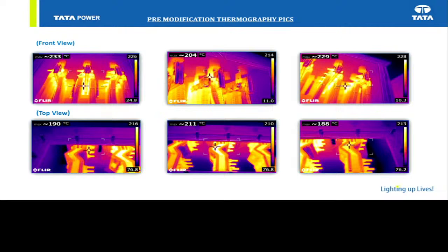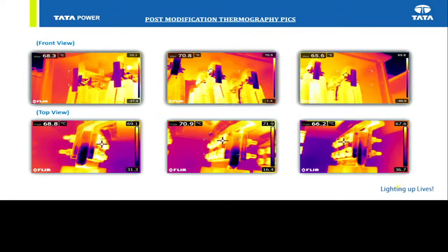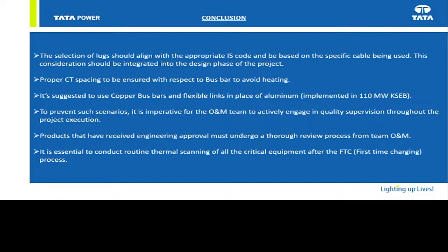For that, we also installed temperature sensors in the LV ducts. But later on, we found no problem. You can see before and after photos. This is the situation, and these temperatures are the actual temperatures at the site. How we took them: we loaded the transformer to full load for, say, 1 hour, then immediately shut down the transformer and opened it. It may take 20 to 30 minutes, and after that this was the temperature. This was captured at 30, it may go to 50 at peak.